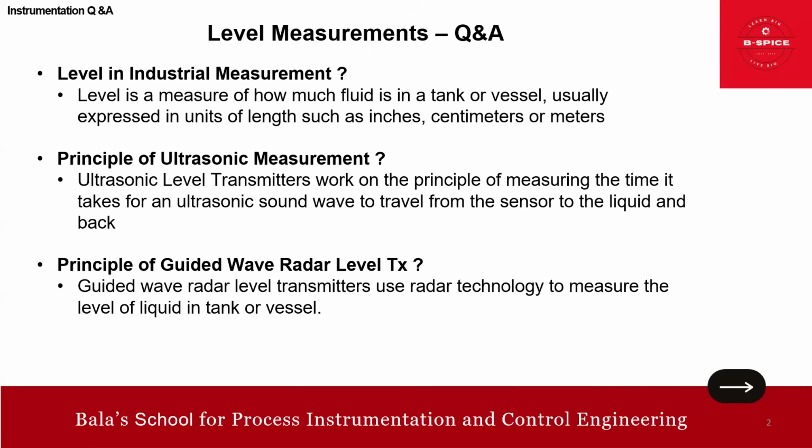Then coming back to the subject, principle of guided wave radar. Guided wave radar uses radar technology to measure the liquid in a tank or a vessel. We call it time domain reflectometry, TDR, or time of flight. The radar pulses are guided down the probe submerged in the process media.